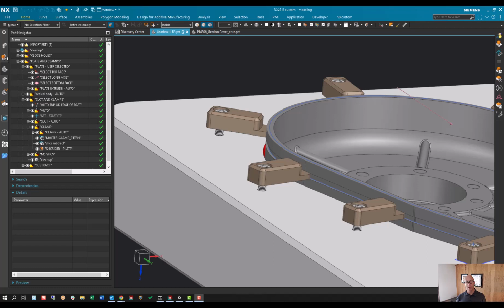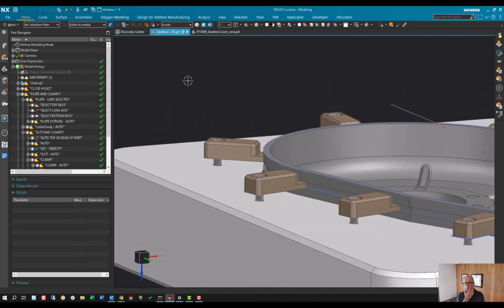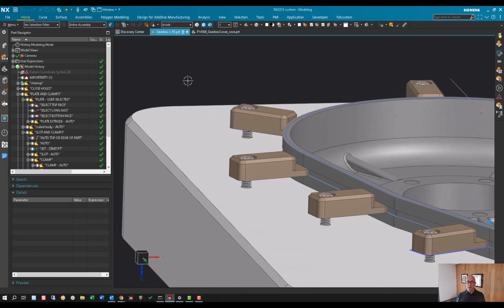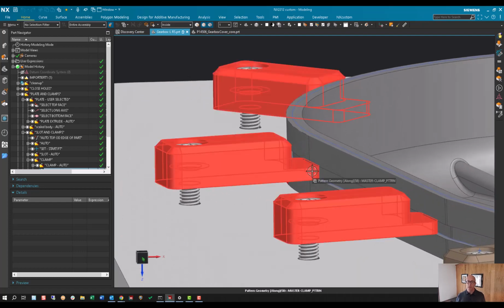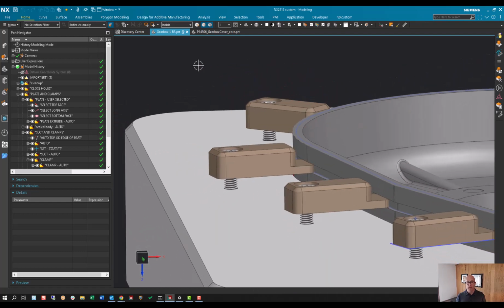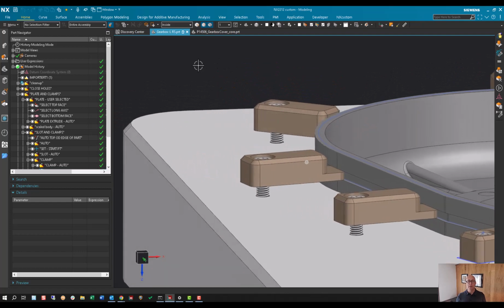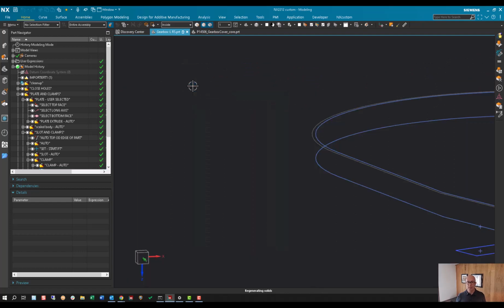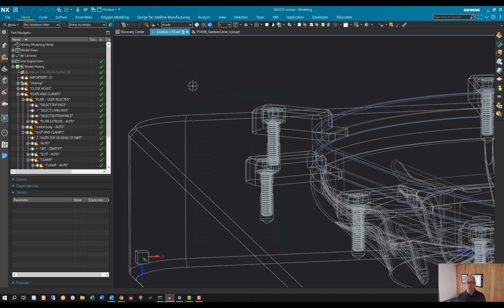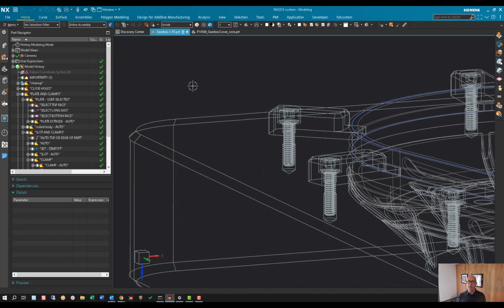It's also the height and the width that have been designed such that it will work perfectly with the T-slot cutter. And so we're removing it. Basically the dimensions are user selectable, but are based on the size of the cutter. We're also making sure that the T-slots will update based on the slot, so that they will fit. We are just adding a bunch of smart design, again, because this can be reused.